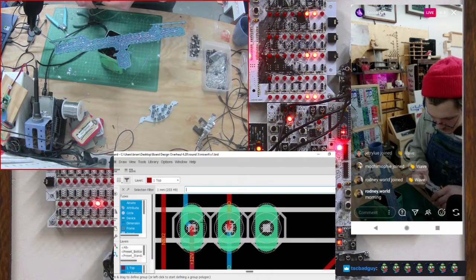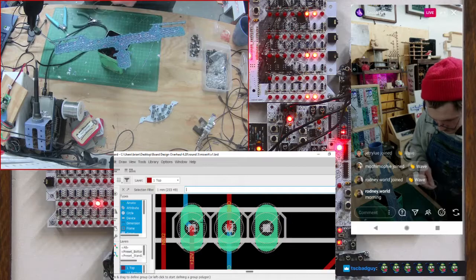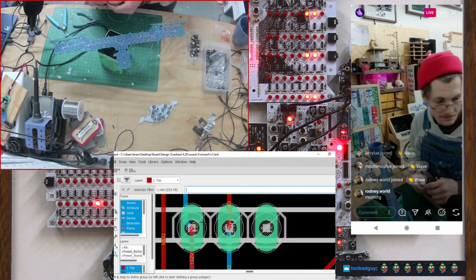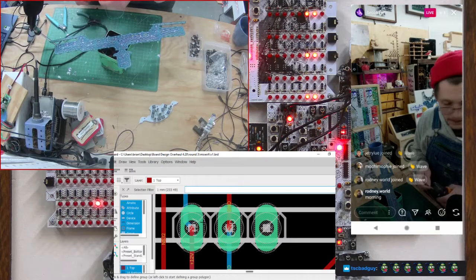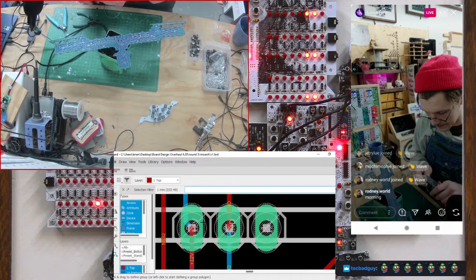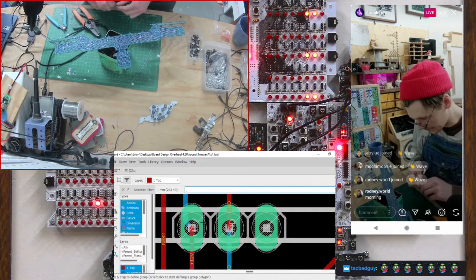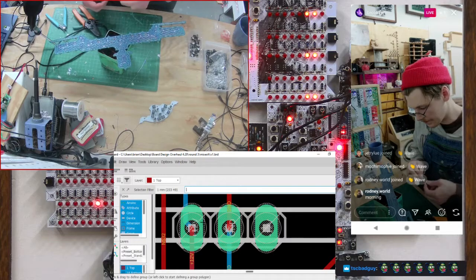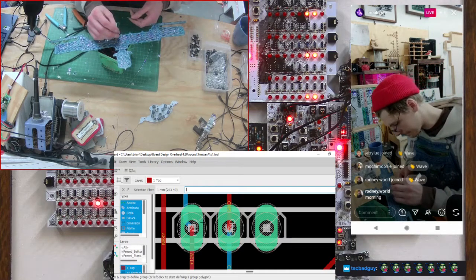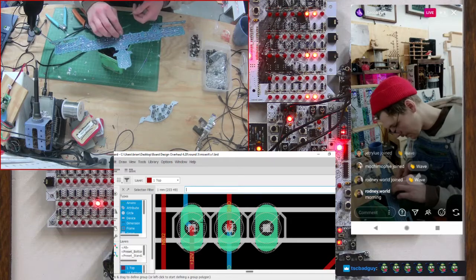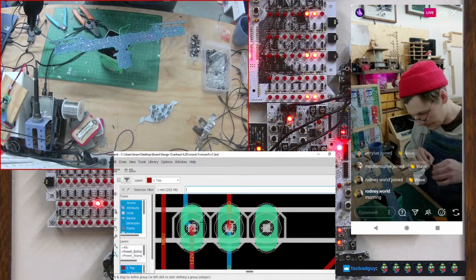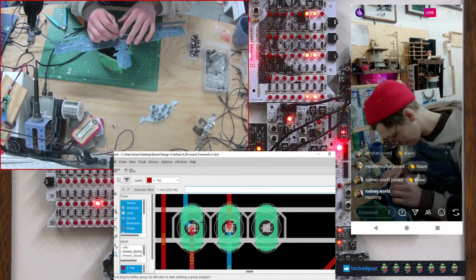Yeah, so the other circuits, they all take plus minus 12 volts because of the sort of fancy ICs. Not fancy, they're very simple and very basic ICs, but because the ICs in them require a 24 volt power differential. But this one, the only thing that's powered on here is the lights, and the LEDs don't need that much power, so I can just run this off of your regular old 12 volts DC.